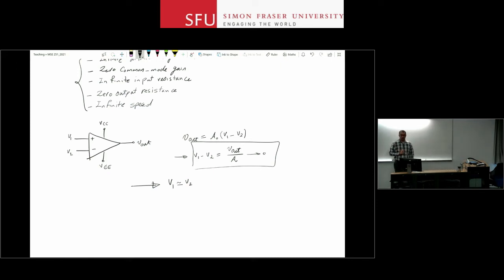We'll show you how this happens, right? So for now, you can always say that, okay, I go and use a signal source V1 and an independent signal source V2 and apply them to the input of the op-amp. Then what? Well, what is going to happen is that your op-amp is going to leave the linear region. It's not going to behave as we discussed so far. So the output is not going to be the difference of the two signals times gain, because the gain is infinite. Usually your output voltage from the op-amp will be either saturated at the top or the bottom, and that's it.